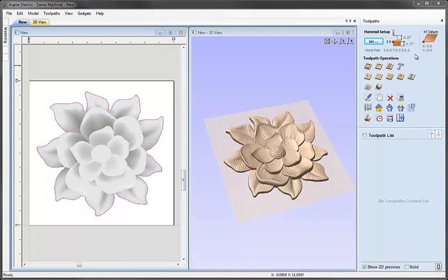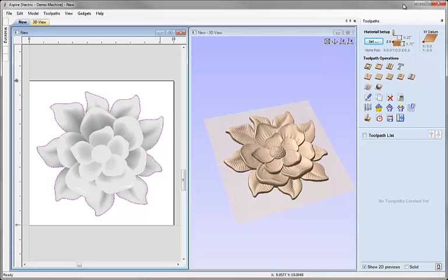At this point, we're ready to start calculating the toolpaths that will actually reproduce this 3D part on our machine. It's worth noting here that you should make sure that if you do plan to cut this, that all the values you've entered for the material and datum setup, for the safe Z, and any parameters you put in for the tooling and the toolpaths themselves are appropriate to your machine, material and setup and are safe for you to cut this.